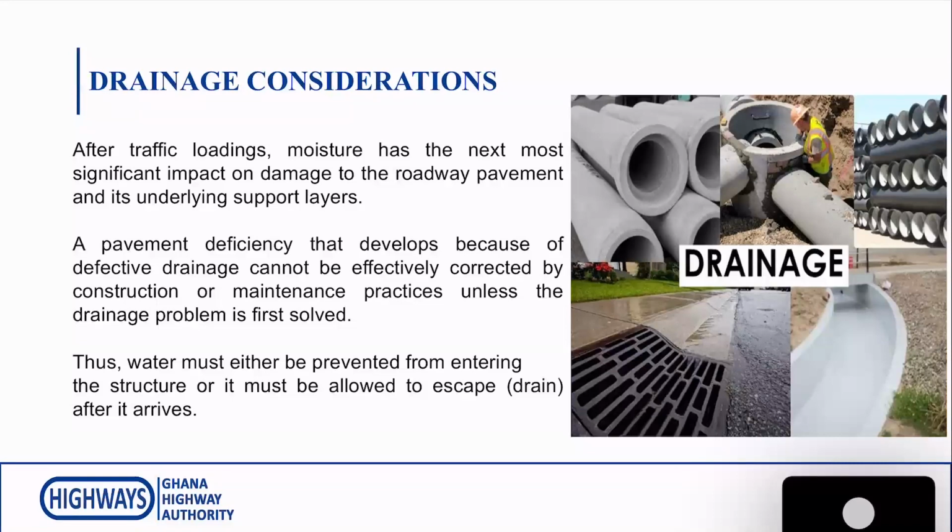And we have some examples all over the place. A typical example is around Ashama roundabout. If you are going towards Afienya, just after the roundabout, you have an area of about 100 meters which is always a bad part, simply because the pavement layer there has been worn off.